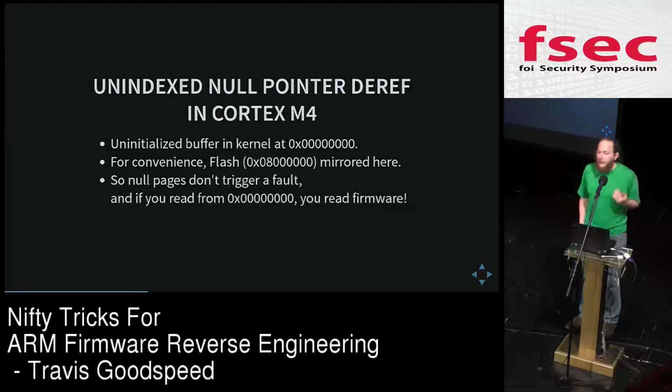Luckily, I'm running on an ARM Cortex-M4. This is an embedded 32-bit machine. It's running the thumb instruction set. And inside of the programming for the radio, you have to specify which memory you would like to read or write. The idea is that you're allowed to read from external memory, or you're allowed to write to internal memory. And when you write to internal memory, you're doing a firmware update, and the firmware updates are encrypted. I didn't have the encryption keys.